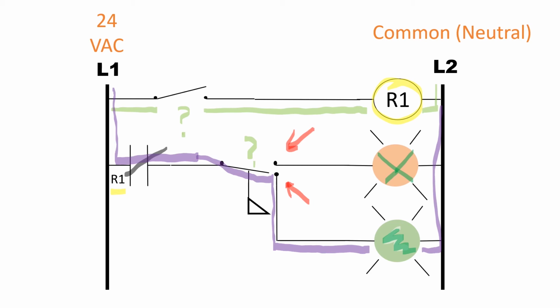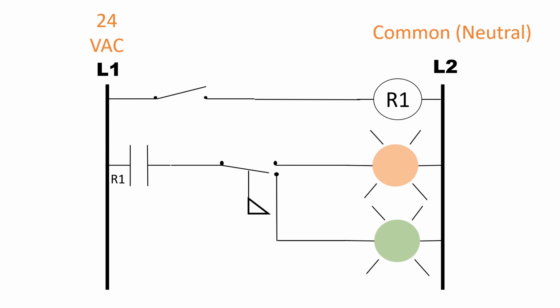In this same circuit, as we follow the current all the way through to the two-position flow switch, we will see in this scenario that the flow is established and allows the current to flow in a different direction. In this scenario, the red indicator light will illuminate.